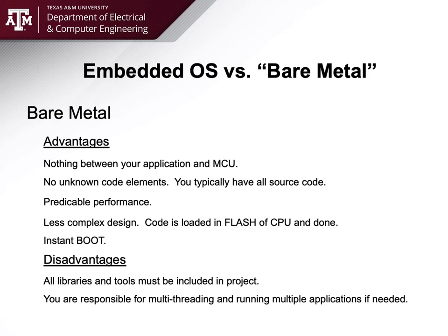Now, in the embedded OS, for instance, with Linux, usually the first application is U-boot, which is kind of the same thing as BIOS on a laptop or a PC. That's the instant boot part, and you could write your own U-boot. I do as well. I have code to actually write U-boot. It's part of when you develop a Linux kernel from scratch, which I've done a few of.